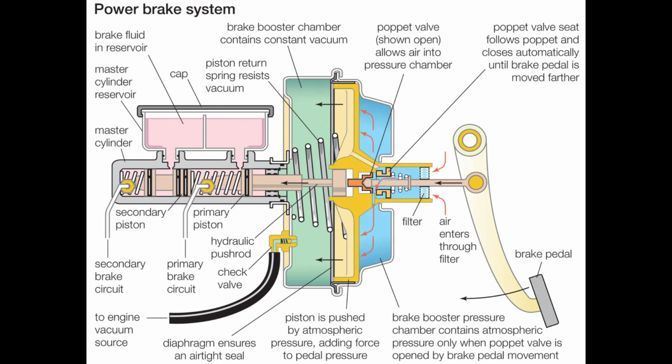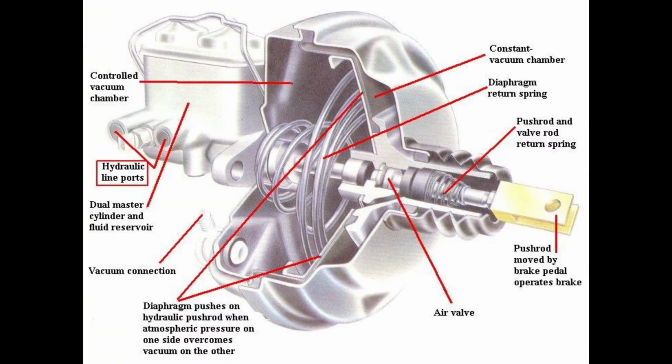This braking system is used where there is a need for power assistance, and is used to reduce the effort of the human. In a car, the vacuum engine is mostly used to create a large diaphragm flex in order to operate the control of the cylinder. Servo braking system boosters are used in combination with the hydraulic brake system. Vacuum boosters are mostly used because they increase the force of braking. Pushing the brake pedal releases the vacuum on the side of the booster, and the difference in the air pressure which is created pushes the diaphragm for braking the wheel.